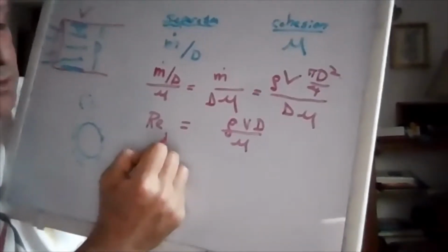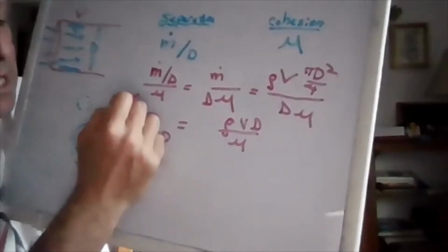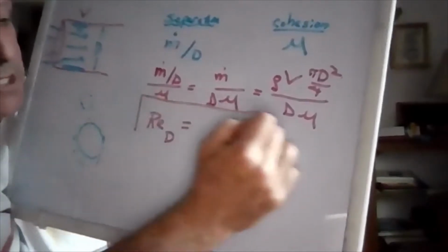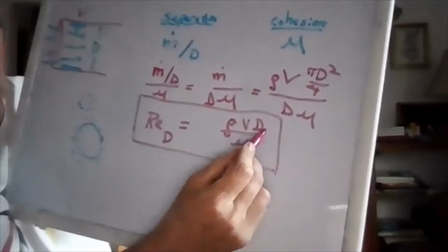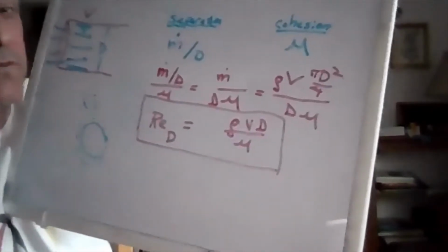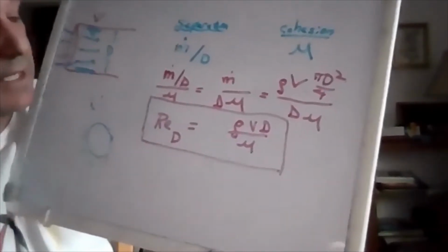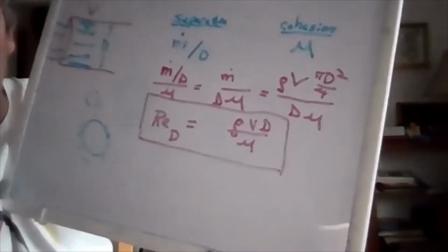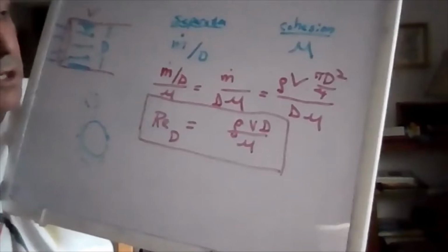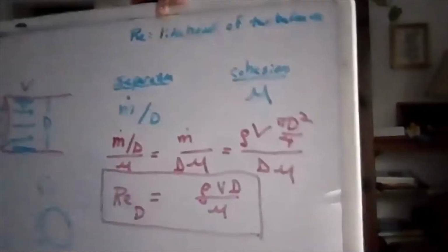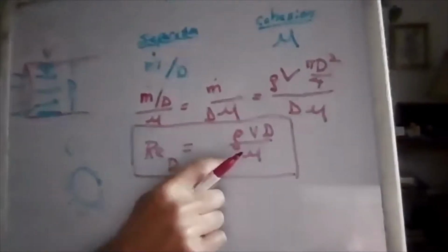In some textbooks, they use D, saying, hey, this Reynolds number applies to pipe flow, which has a diameter. There will also be Reynolds numbers where this is an L, and it might stand for, say, the length of a wing or something like that. Okay, so for pipe flow, if we're assessing the chance that there's going to be turbulence, we are going to think a little bit about mass flow and diameter and viscosity and visualize what's going on, but pretty quickly we're just going to go in and calculate that parameter.